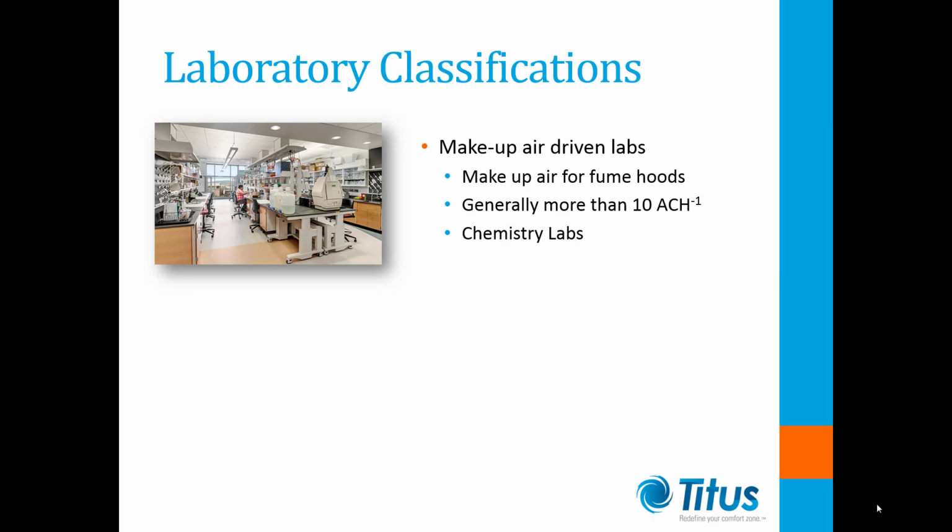When designing HVAC systems for labs, we can break them down into two classifications. Labs that are fitted with a high density of fume hoods will require large amounts of makeup air delivered from the central air handlers to maintain the required pressure in the lab. These types of labs may require more than 10 air changes when all the fume hoods are operating, and are often referred to as makeup air driven labs.